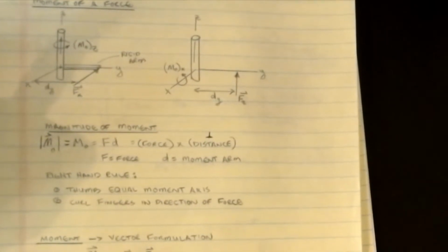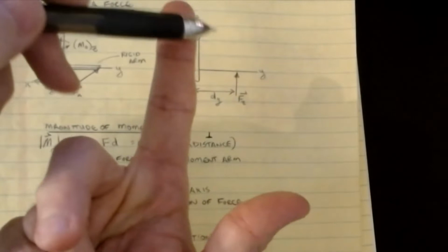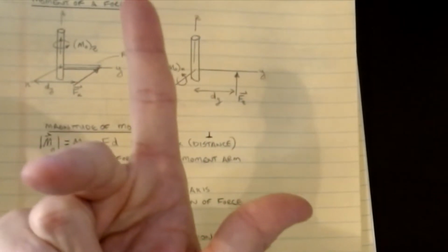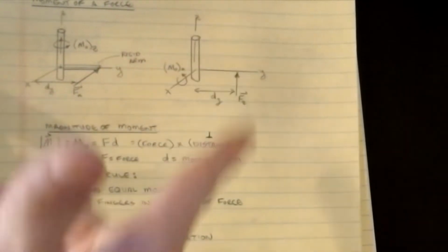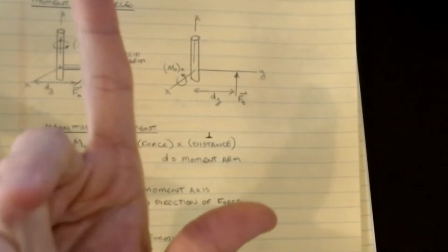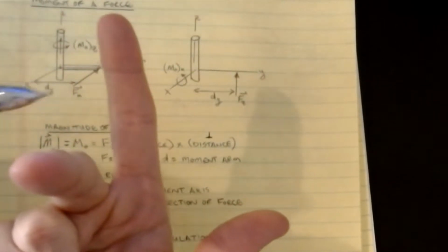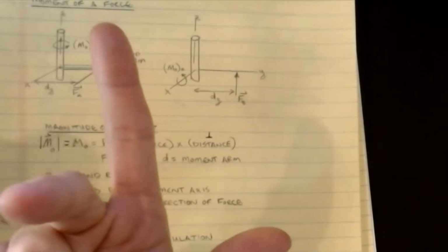We also outlined a right-hand rule for determining notation. I showed you that one, so keep that in the back of your mind. You'll find in statics there are a lot of right-hand rules that come around. We've got the right-hand rule for the Cartesian coordinate system: x on the thumb, y four fingers, z is up. All those would be the positive directions. Now I can turn this any way as long as those stay perpendicular to each other. I can orient my axes however I want. But I need to do that in order to make the cross product work, and you'll see that the cross product becomes one of the ways to calculate vector moments.